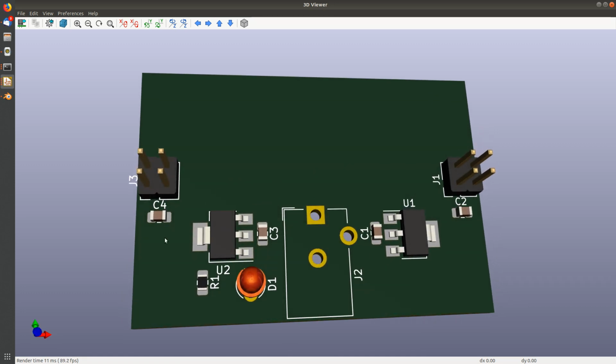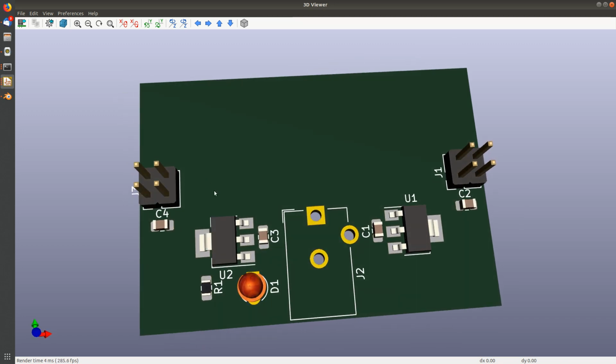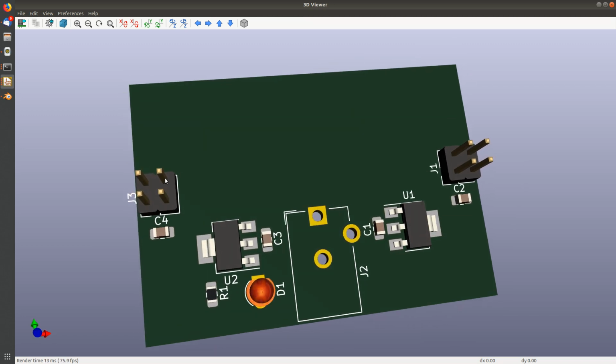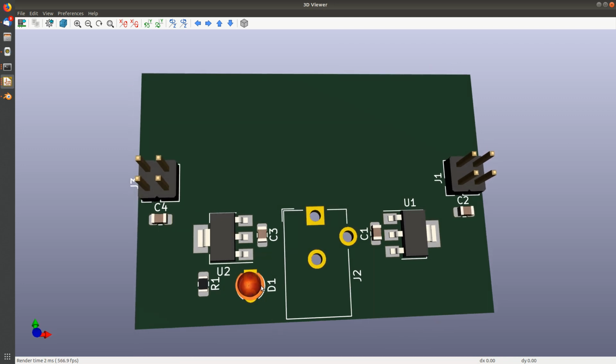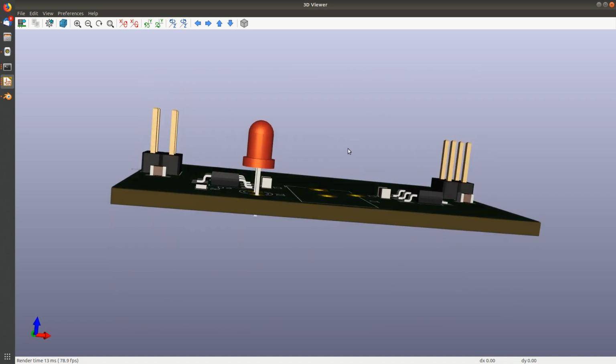The white drawings on here, these are the silkscreen drawings I mentioned on that silkscreen layer. J3 over here is not on the PC board, and it would be annoying if you made it this way. You're free to do so. You just won't have a labeled connector over here. So one of the things we need to do is make sure that we move around our silkscreen legend, these parts indicators, so that we can see them, that they all look nice. All right, so this, roughly speaking, is our board.